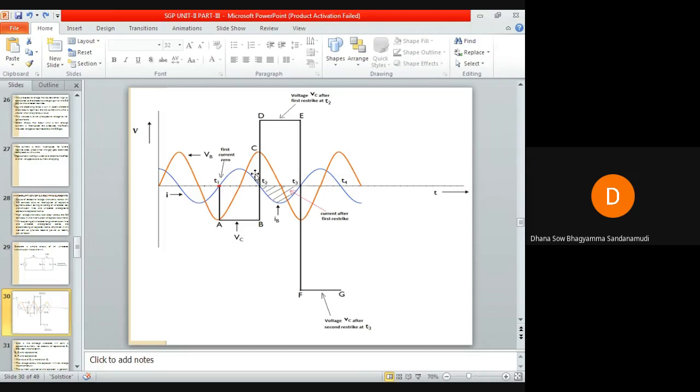So within such a short interval of half cycle, the breaker has been subjected to a severe condition with the result that breaker might restrike. So when voltage across the stray capacitor has doubled, that voltage will appear across the circuit breaker contacts. So there are chances for the restriking of the arc across the circuit breaker contacts.